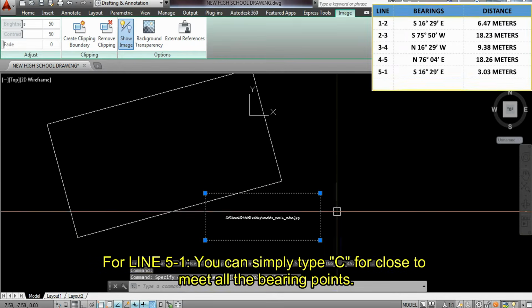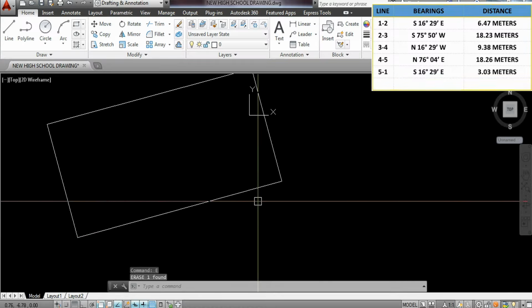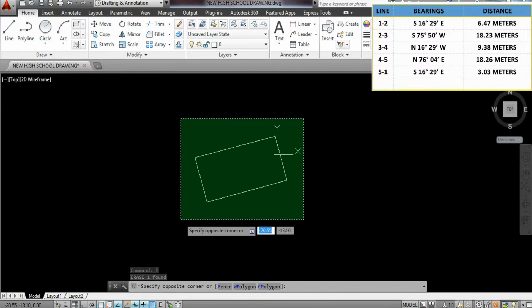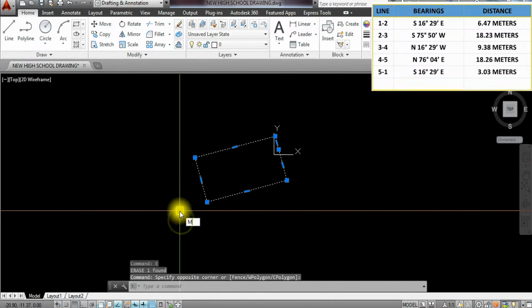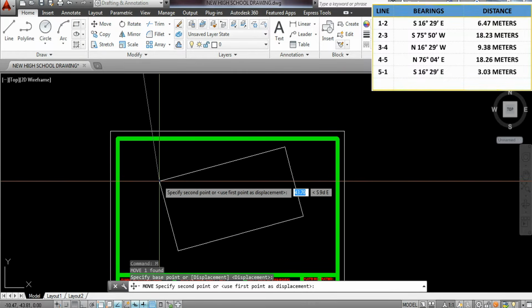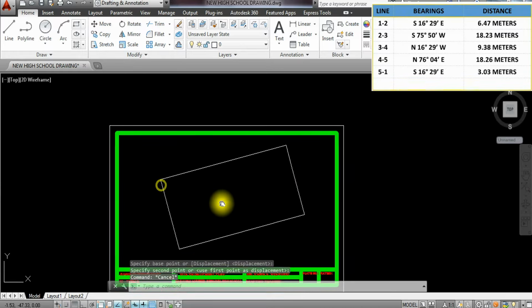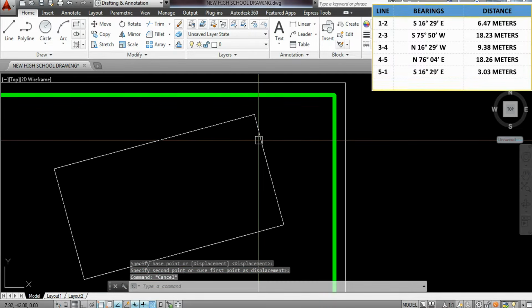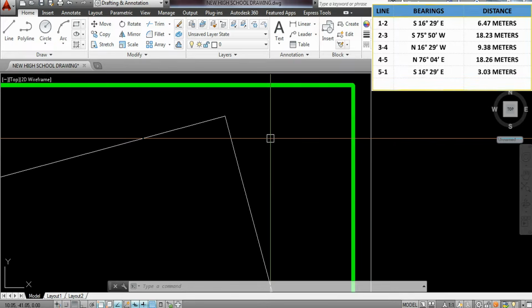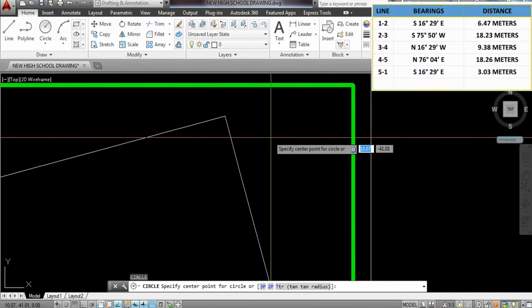So I'm going to move this drawing here or erase this drawing here and then transfer this output to our AutoCAD, to our borderline. So, I'm going to move this here. Okay. So, after which, remember, this is a 5 bearing point. Then, after that, we have to place circles on every bearing point that we have.